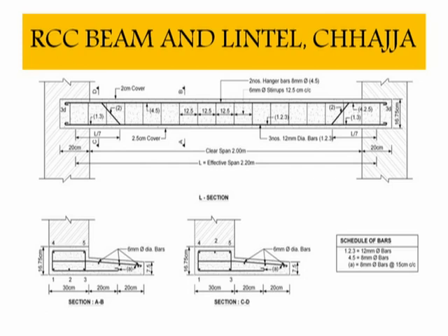The projected part outside the wall which is constructed of RCC is known as the chhaja, and in the wall itself, at the bottom there is an RCC beam-like part which is known as a lintel. Normally the lintel and chhajas are combined for the case of windows. When a window is constructed, the lintel and chhajas are combined, so they are cast at the same time.